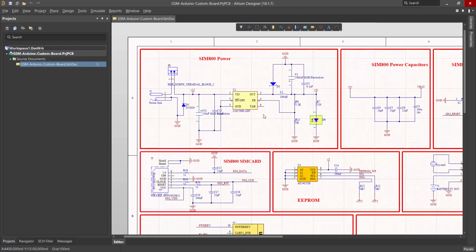Another reason that we use two types of regulator is noise. DC to DC converters, switching converters, produce some high frequency noise on their output, okay, because of their switching function.